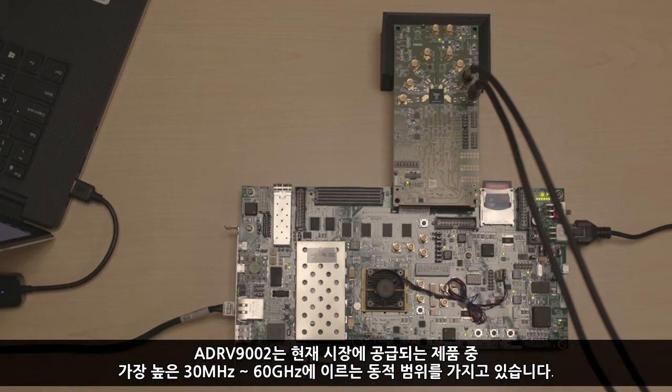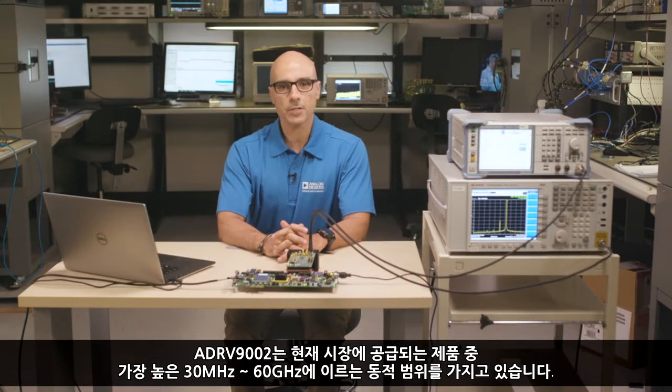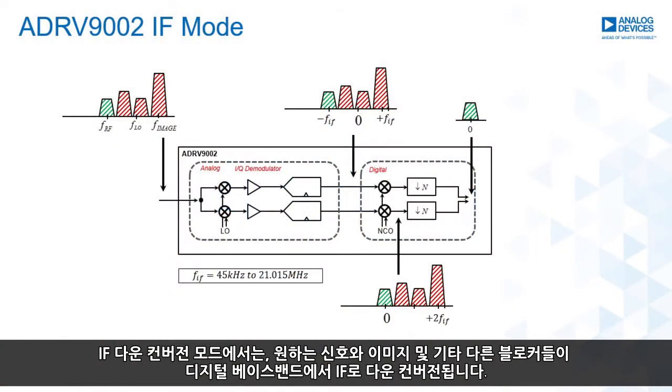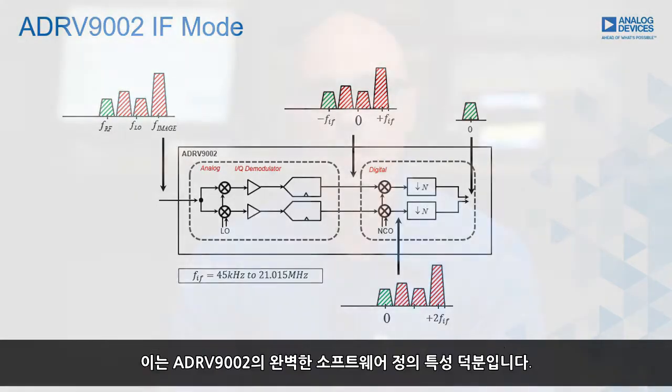The Adrv9002 has the highest dynamic range on the market today, from 30 MHz to 6 GHz. It achieves exceptional phase noise and blocker rejection performance. The receiver has both zero and IF down conversion capability. In an IF down conversion mode, the desired signal, its image, and any other blockers are down converted to an IF in the digital baseband. The desired signal is extracted, the blockers are filtered, and the image is rejected, all in the digital domain. This is thanks to the true software-defined nature of the Adrv9002.